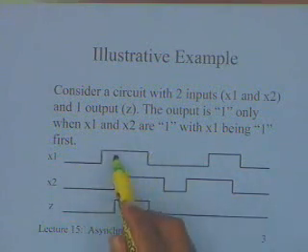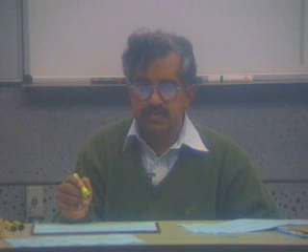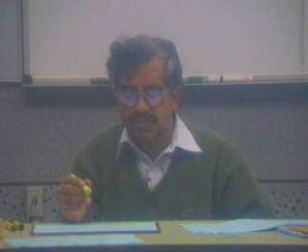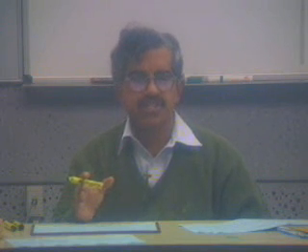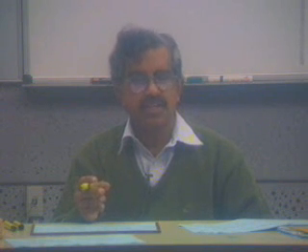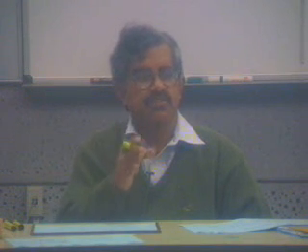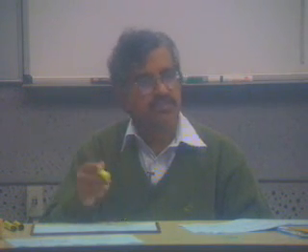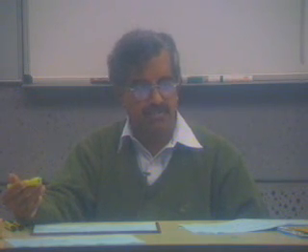So isn't it similar to a problem with pattern matching when we are having just one input and seeing just the last two inputs? No, not one input. So now we are talking of two inputs. When you talk of a change in the number of inputs and their timing relationship, there is no direct equivalence. But you can say that with two inputs also you are looking for a pattern. The pattern that you are looking for is, let us say, 1 0 followed by 1 1. So there is a method of modeling it and implementing it as a sequential state machine.